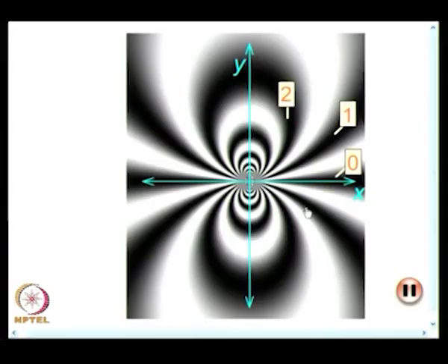See, in none of the problems in theory of elasticity do you really question the stress function. You take a stress function and then look at sigma x, sigma y, tau xy and satisfy the boundary condition. In this case, we have done all that, we have taken a stress function, it satisfies the biharmonic equation, and it satisfies all the boundary conditions. So, we have not made any mistake in the mathematical analysis, but finally we are getting a solution I am sure you have already seen the photoelastic fringes, we would see them again, it is nowhere compared to that.